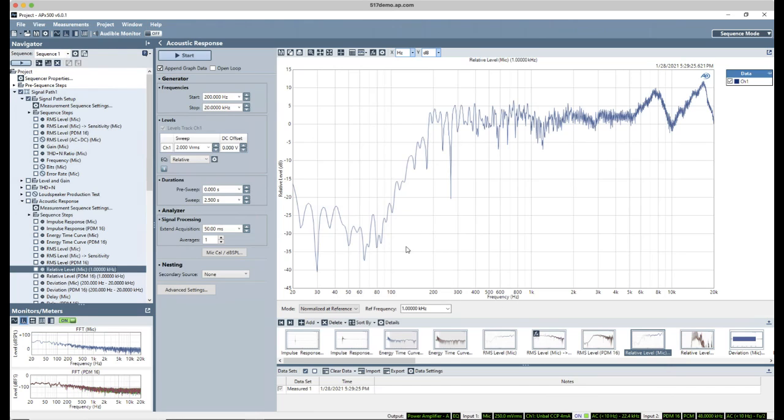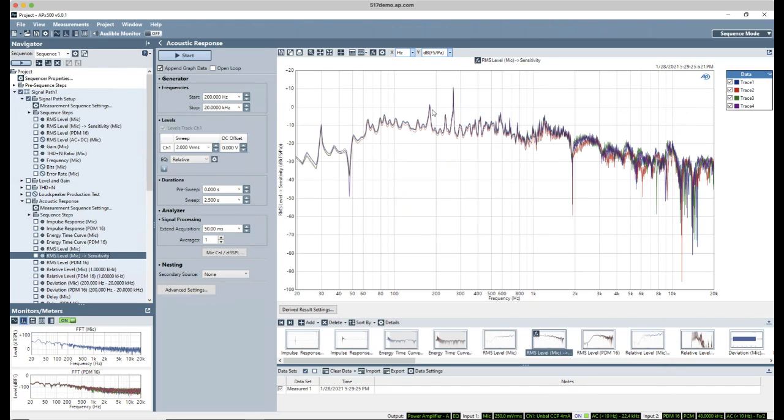So actually, this is a real situation that happens from time to time. We make measurement microphones, but there isn't anything called a measurement speaker. And the big advantage of using a reference microphone is we can still get our result, and it subtracts or eliminates the speaker from the equation. Quite literally, it's simply divided out.